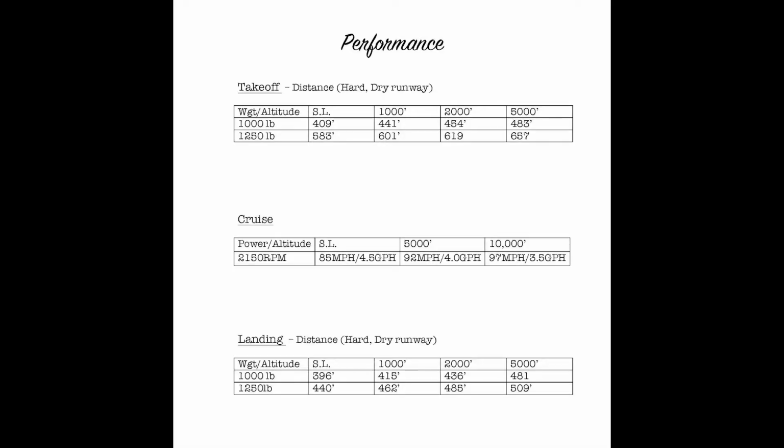Section 5, which we'll talk about more in a little bit. Actually, we'll talk about this in what, from your perspective, will be the video after next. Aircraft performance. Section 5 in the POH gives us all of the data and graphs that we need to be able to calculate the aircraft performance: takeoff performance, cruise performance, landing performance, all those numbers that we need to know so that we have enough engine power, that we're not too heavy to be able to take off and land safely, and that we have enough fuel to fly the distance that we need to go.